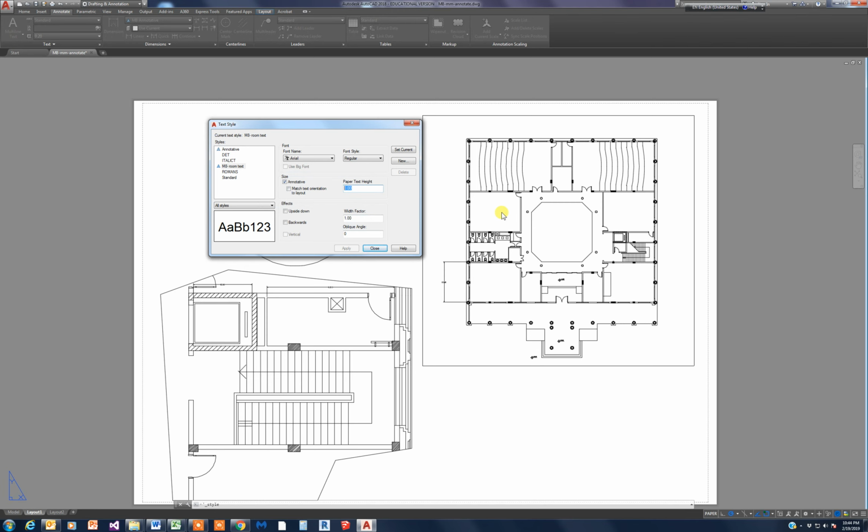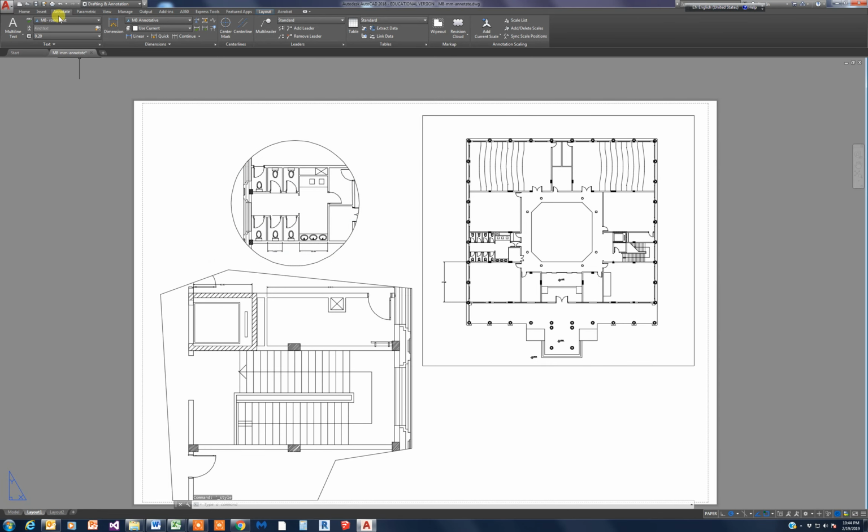And I'm gonna decide what is the size if I start naming the rooms, yeah. So I think about 3-4 millimeters should do, so I'm gonna go for 4 millimeters, and I could change the style if I want to any style, and there are different options you could play with, but important, look here, it's annotative. This is how it works here. This is what controls it, and I said it's already current. Okay, so if I look here, it's M8 room.